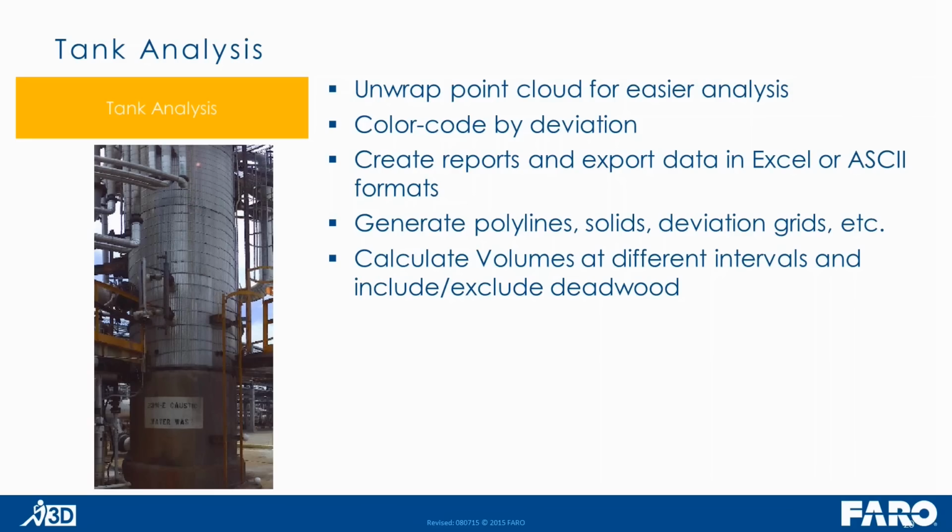Now in that Excel report you can do volumes or volumes at specific height intervals, and you can also do around the circumference. When you bring it into Excel, a lot of our customers, in my experience, are doing very short vertical increments and maybe a little bit more lenient horizontal increments. But you can get a deviation analysis on the surface, or a deformation analysis on the surface. You can also get volumetrics at every single height, and it'll give you the specific volume of just that 1/8 inch, for example, and it'll also give you a running total.